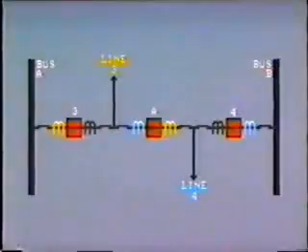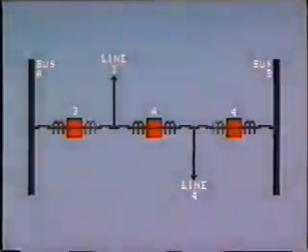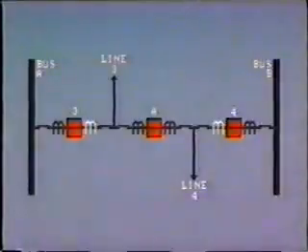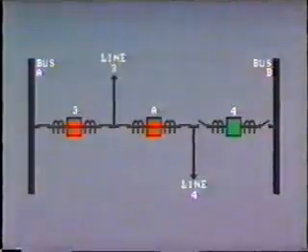be provided. Line relays are served by the outboard CTs of the line breakers. Bus differential relays are served by the outboard CTs of the bus breakers. If breaker 4 needs to be removed for maintenance, then simply open and isolate breaker 4. Lines 3 and 4 will now both be fed by bus A.